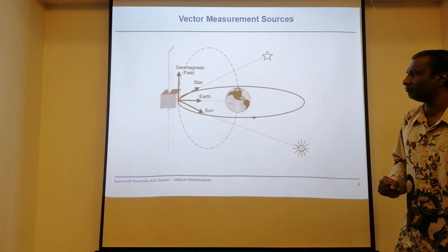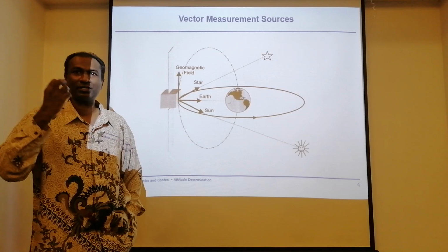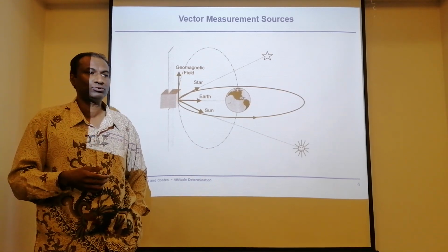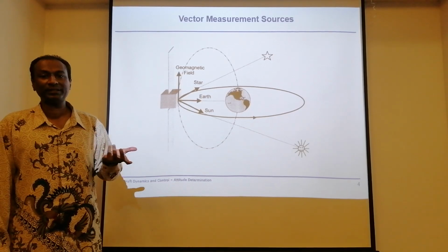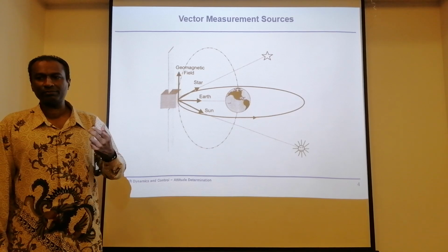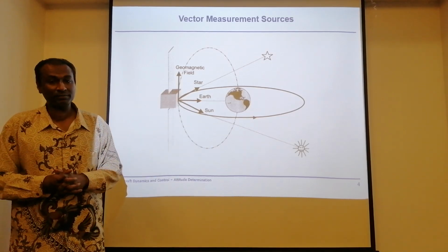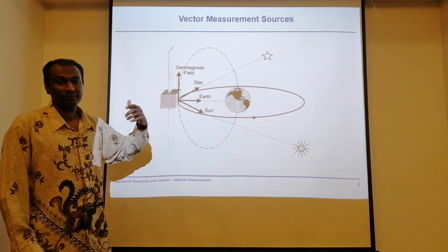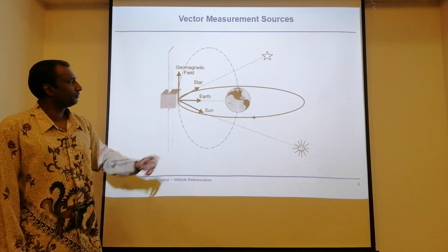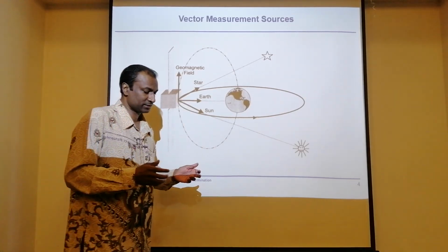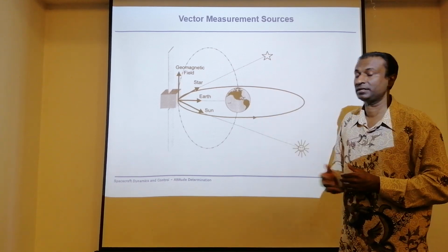Go on. Now, if you look at the satellite as it flies, we may need to use some landmarks or objects in space which can help us do the actual estimation or determination. The sun can help us, because we have sun sensors. In satellite technology, you've been exposed to all sorts of sensors on board a spacecraft. Sun sensors could play a good role here, but unfortunately they don't work during the eclipse phase. Planet Earth itself can help, because we have horizon sensors, which can always help us estimate our attitude. We have stars too: like seafarers, who use the formation of stars to navigate when sailing, we can use that as well when flying.